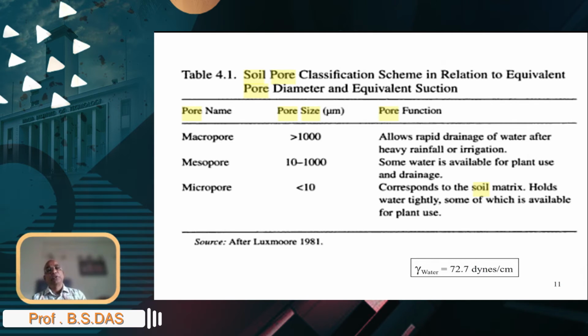You have micropores and the macropores, and the largest pores are macropores. If you take the radii of these and put that in that relationship, the capillary rise equation, you see that the height of water in the capillary, if it's just a single capillary, would go